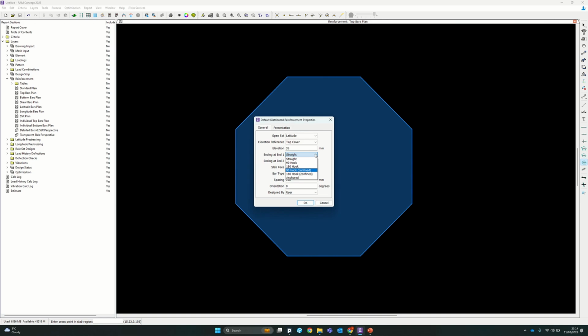But a very, I'm not sure if it's a bit of a cheat way of doing it though. What I typically do is just click on anchored, and it basically assumes that all of the reinforcement that you're placing in here has headed terminators on the end of it, and therefore it develops the anchorage length automatically.